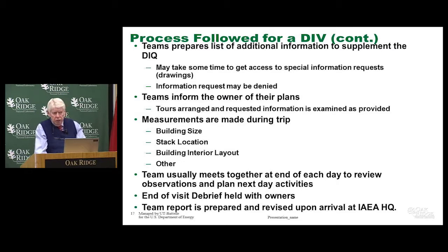Now, during the trip, measurements are almost always made of the building sizes to conform to the drawings, locations of things like the stack, and then the layout of the interior. On subsequent visits, this information is updated in the DIQ, and then if there are any changes in the building layouts, these are identified during the verification process, and either explanations are made or revisions to the DIQ itself are made.